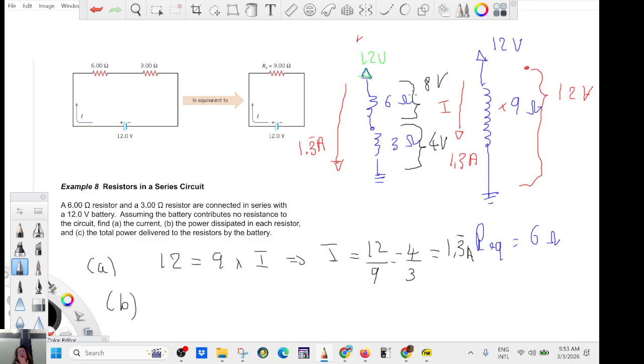So this is called Kirchhoff's law for voltage. This is a circuit in series, and you see that the sum of all the voltages equals the voltage of the power supply. Once you have 8, you know this one will be 4 because 8 plus 4 is 12. But you have to measure the height. It's like you start from 12 yards and you drop by 8, so 4 is left.